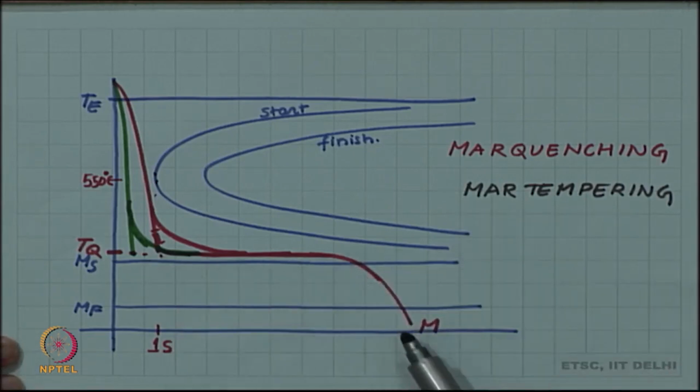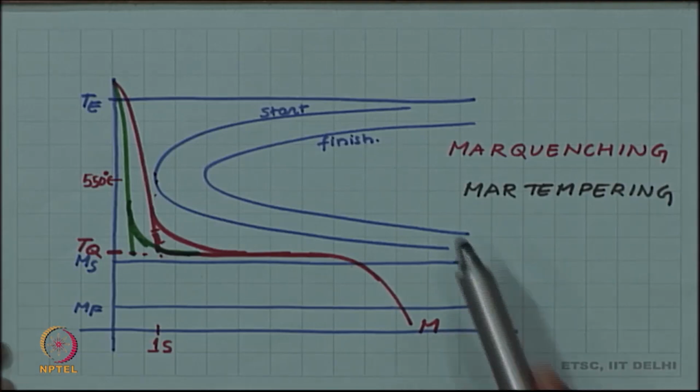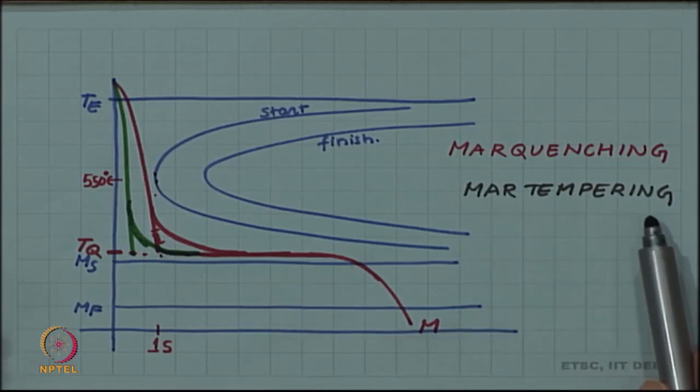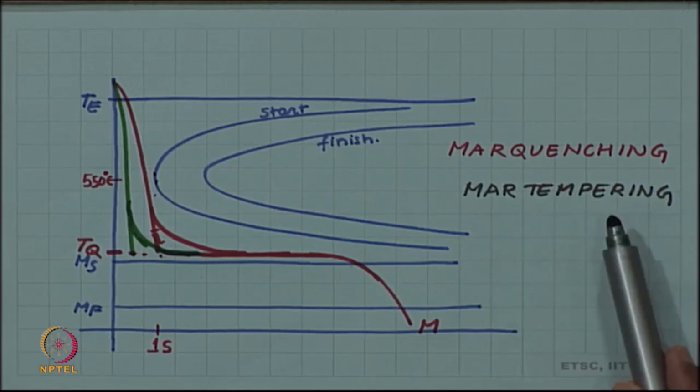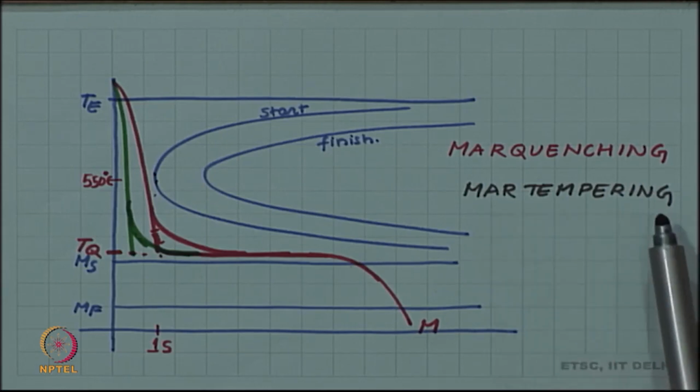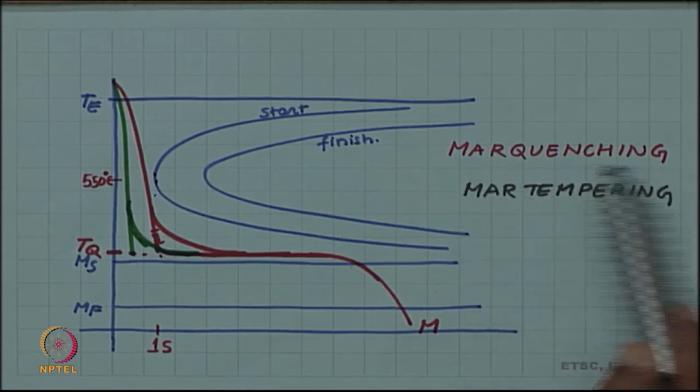Martempering can also be used for this process, but remember we discussed tempering, and in tempering a quenched martensite was again reheated, but in Martempering there is no such step. So, sometimes Martempering can confuse us with tempering. There is no tempering involved. A Martempered specimen again has to be heat treated and tempered. So, Martempering does not involve tempering. Tempering has to follow Martempering. So, I will recommend Marquenching as a better word for this process.